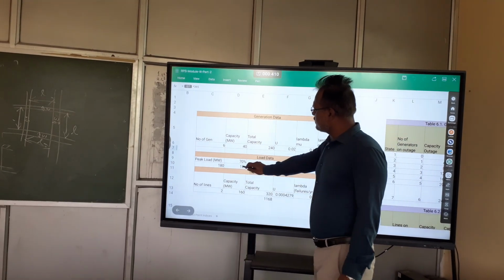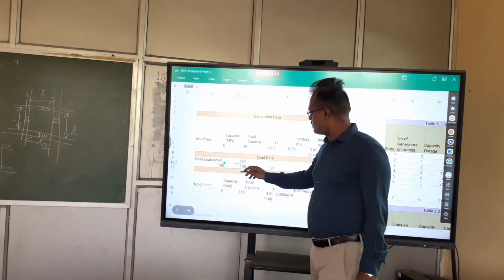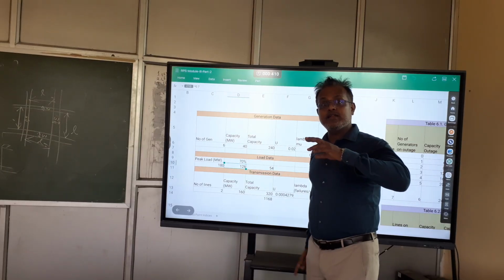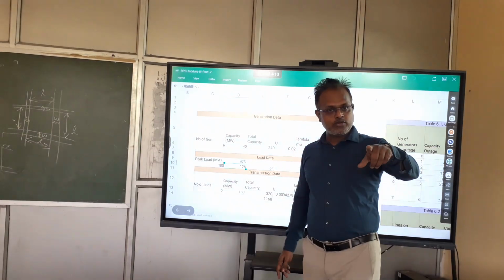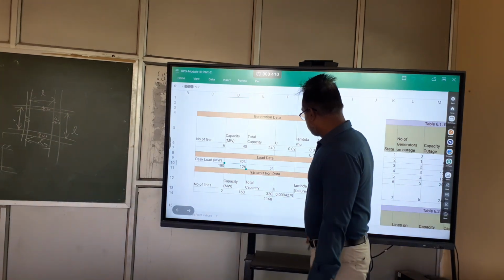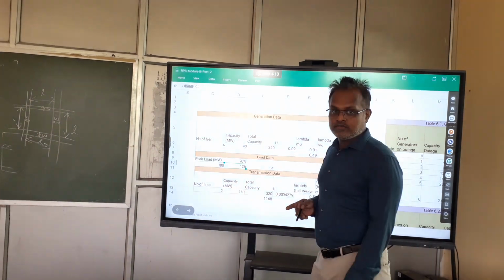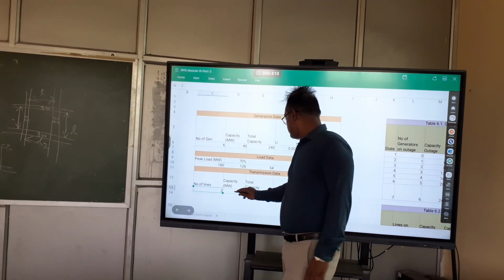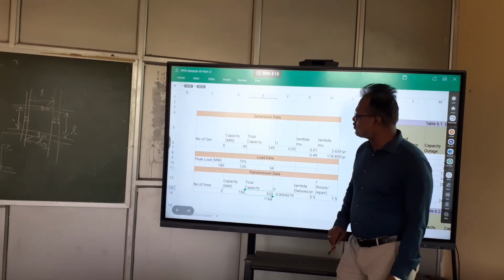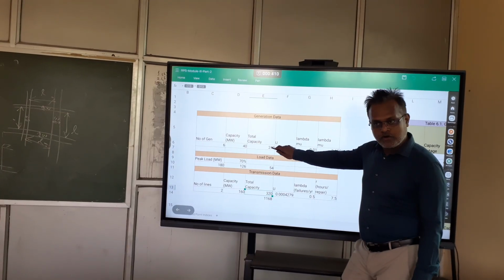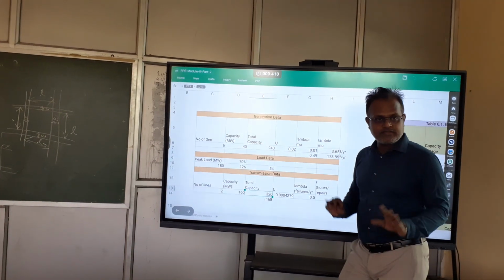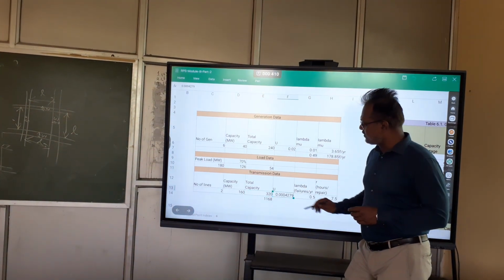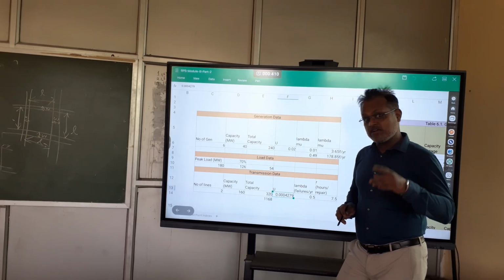You told me 126, right? So this is 126. This is for the load duration curve. But as I say, we won't go further. This is exactly similar to what we did for the generation system. The main difference with respect to generation system reliability evaluation is the transmission line. Here there are two lines having total capacity of 320 megawatt. Our generation capacity is 240 and transmission is 320, so we are safe. Transmission capacity is much higher and its outage is very low compared to generation.